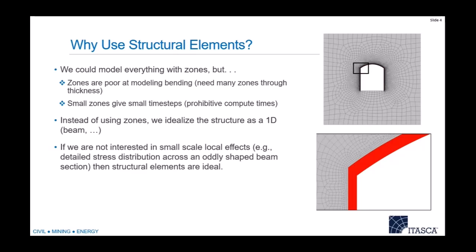Basically, what I'm saying is this is going to create extremely small zones in your model, and typically those zones will be stiffer if it's shotcrete, which all points to this model taking a very long time to run. Anytime you have very stiff zones, very small zones, that will dominate your time step. So you could be running this model where the time step has to be reduced to a very, very small number, and it takes forever to run.